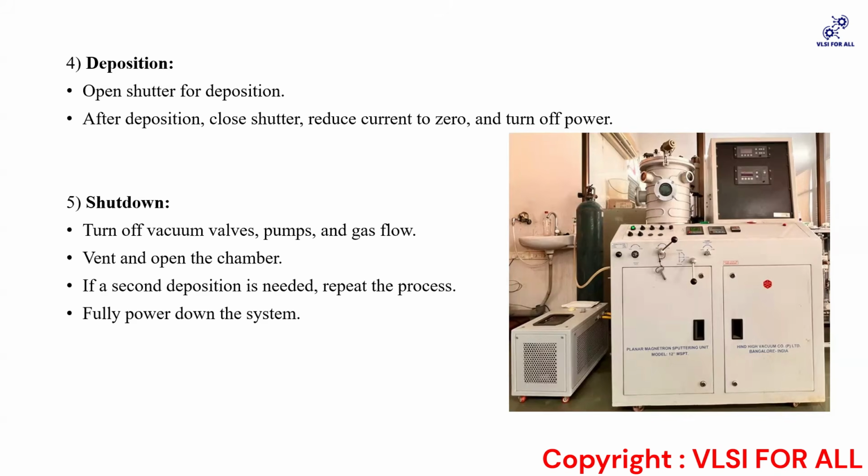Then eventually clean the chamber, because multiple processes have been done, so there might be fumes or different materials spread into the chamber. We need to clean the chamber even after one process is completed. If we want to deposit a second layer, then repeat the process again, and then fully shut down the device.